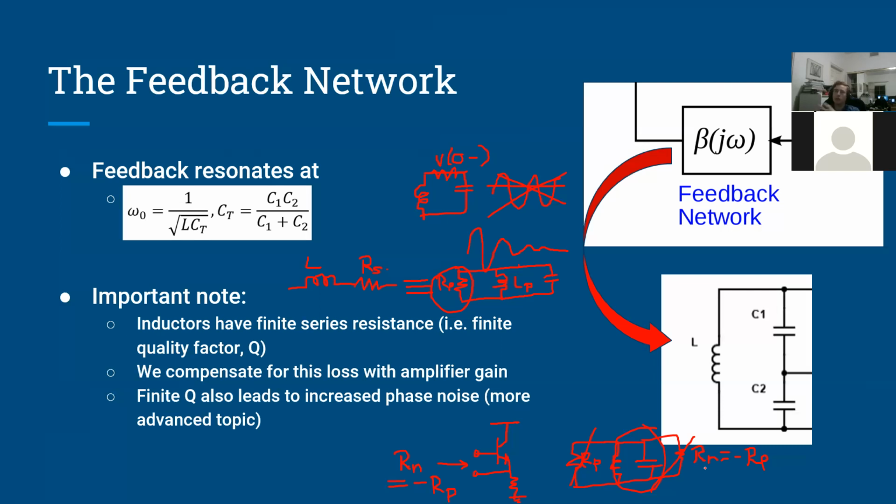Well, when you use the oscillator in a system, you do care because, if you're driving a mixer with your oscillator, sometimes the mixer requires a certain amplitude level to function correctly. So you don't want your amplitude to be some random number, and you can control the amplitude, but the math is really hard to calculate what the amplitude will be. So I'm not going to talk about that here.